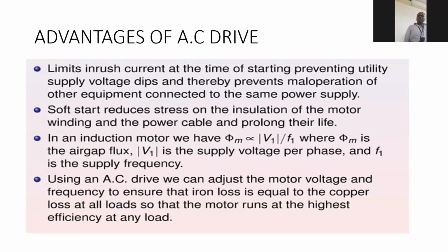Thank you. So here, what are the advantages? That is the main concept of our AC drive. According to the advantages of AC drive, there is limiting of inrush current at the time of starting, whereas it can prevent the utility supply voltage depletion, and thereby prevent the operation of other equipment which is connected to the same power supply.